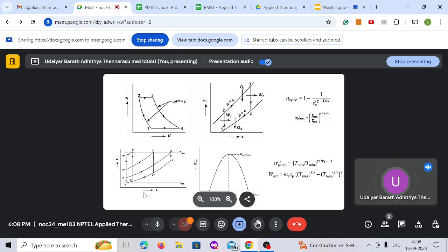practically speaking, you require a bigger sized compressor, and other equipment sizes go up. So increasing your pressure ratio is increasing your component sizes. So from a capital point of view also, you have an increased cost out of going to an increased compression ratio, and also even though your efficiency is increasing, your net work produced is decreasing.